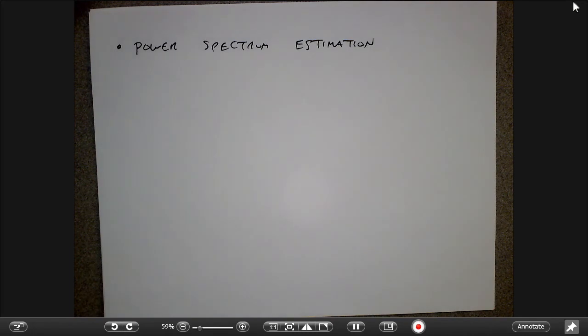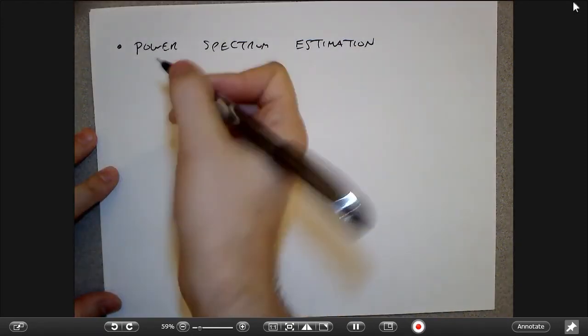So it's a way of getting frequency analysis from the signal without doing a full-on FFT. It's a different route to getting frequency analysis, and a coarser or smoother frequency analysis than you get with the FFT. But some of you, I think, are using it in your projects to get the basic peaks of things in the frequency domain without taking a full-on FFT. So there are different ways of doing this, and that's at the back of the book.